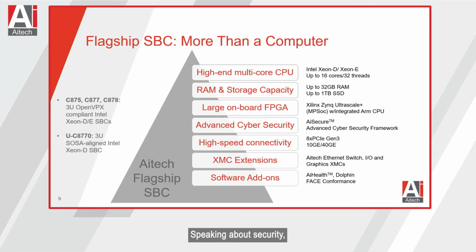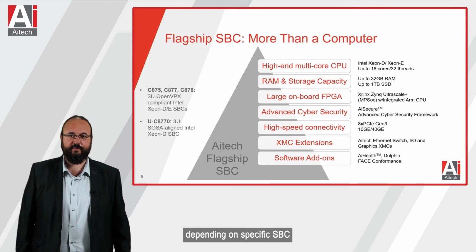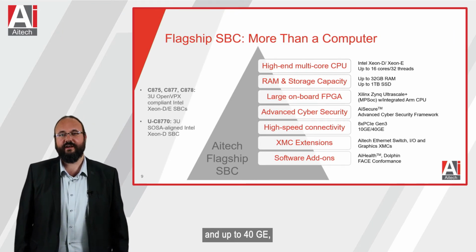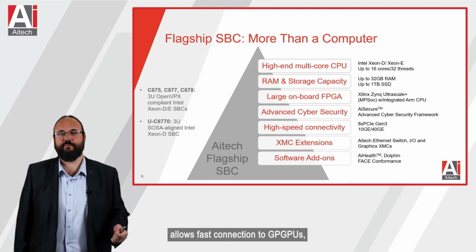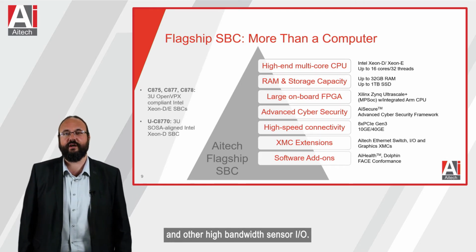Speaking about security, iTech flagship SBCs feature an advanced iSecure cybersecurity framework, which was covered in the previous presentation by our VP of R&D, Boris Bayer. High-speed connectivity, currently supporting up to 8x or 16x PCI Express Gen 3, depending on specific SBC, and up to 40 gigabit Ethernet, allows fast connection to GPGPUs, high-resolution GigE Vision cameras, and other high-bandwidth sensor I/O.